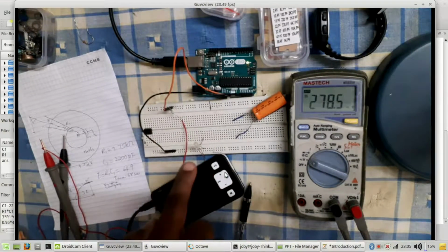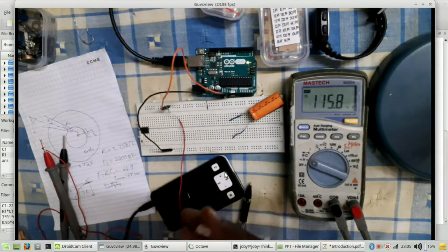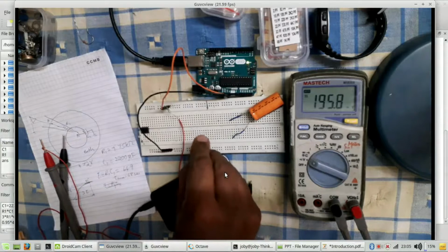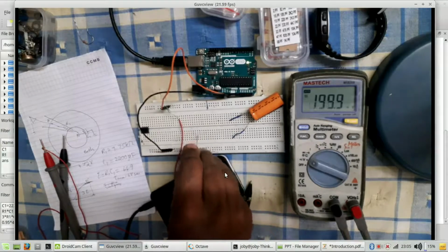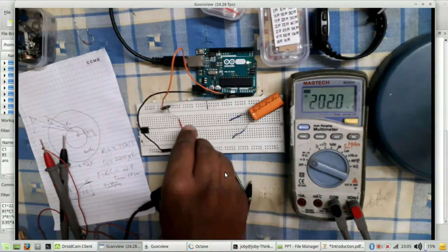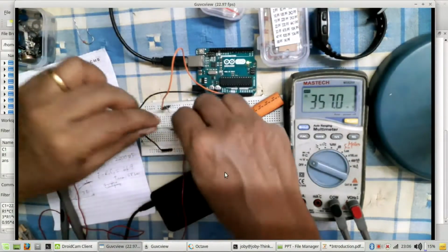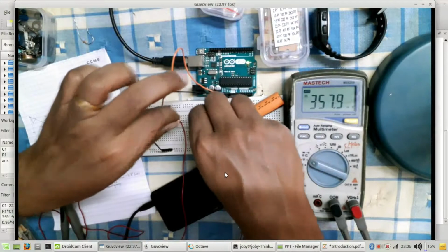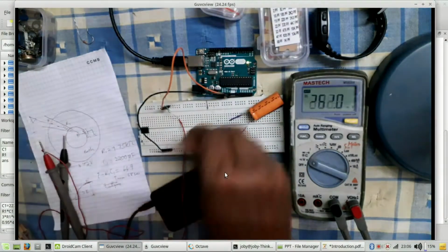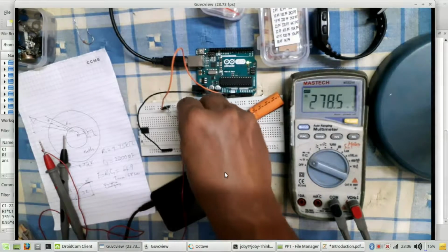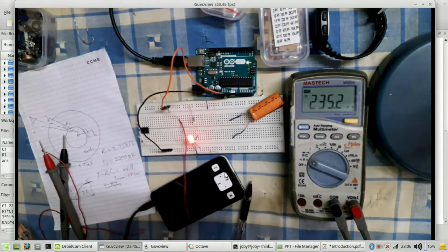So we will use this LED to test it. This LED is a light emitting diode. I have put its cathode here and anode here. Now I'll use this 470 ohm resistor to power it. So let us see whether it works. I'll plug in a point here, then I'll connect it to the Arduino power source. Yeah, it is lighting up, as you can see.